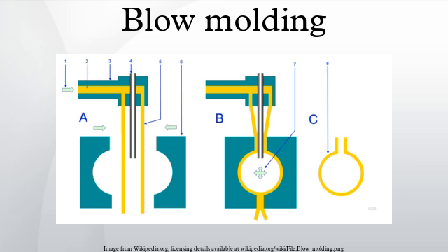The injection blow molding machine is based on an extruder barrel and screw assembly which melts the polymer. The molten polymer is fed into a hot runner manifold where it is injected through nozzles into a heated cavity and core pin. The cavity mold forms the external shape and is clamped around a core rod which forms the internal shape of the preform. The preform consists of a fully formed bottle jar neck with a thick tube of polymer attached, which will form the body. Similar in appearance to a test tube with a threaded neck.